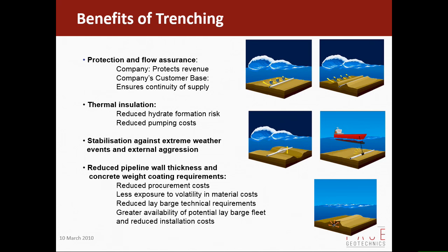Stabilization. Pipelines are subject to loads due to waves, particularly in shallow water. It's not really a significant thing in deep water environments, but in shallow water you can get quite significant loads on the pipeline which need to be resisted. As an example, the Nord Stream pipeline was designed as a surface laid pipeline. They did some more sums and decided they had to trench it, which cost the client quite a lot of money. And then again, by trenching, you can reduce the wall thickness and concrete weight coating requirements, which is another factor.